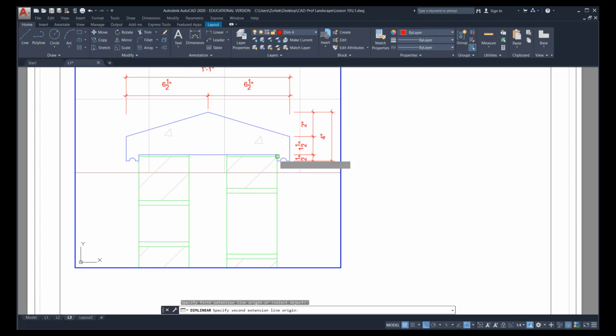I've noted it as a 1/4 inch. I've indicated it as an 1/8 inch. Let's correct that. I can do that right in that viewport using stretch. And again, this is something we have to be very careful what we're picking in order to make this work right. This will take some skill. I'm going to stretch a window right across there. So where did I pick? Just above that mortar line, and I'm going to go just below it.